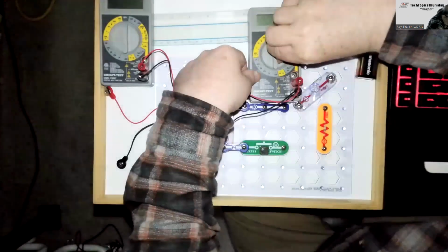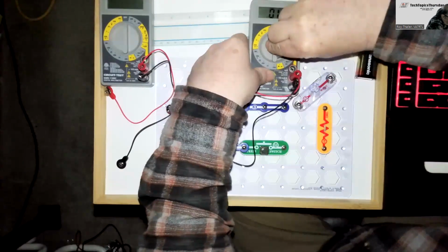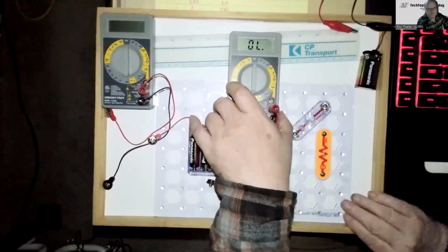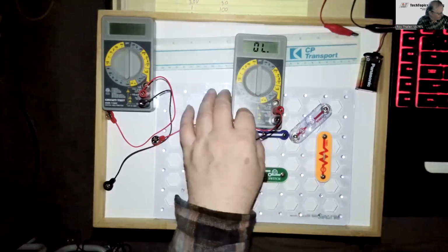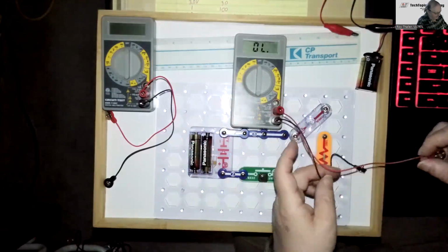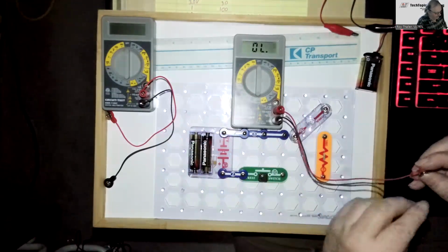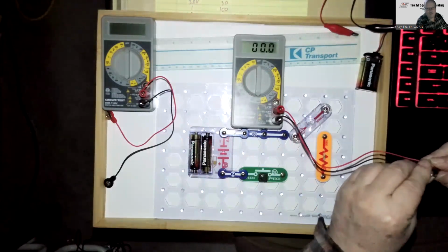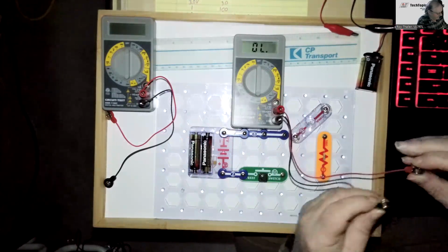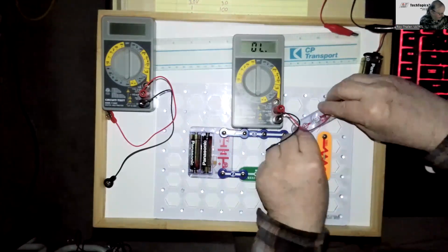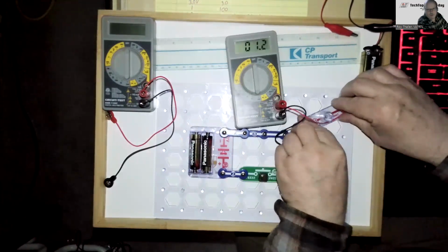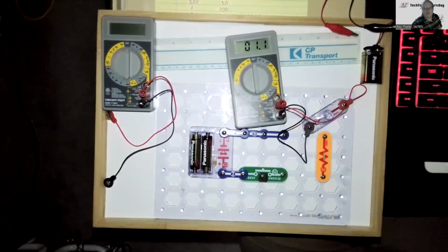And if we turn our multimeter to resistance, we will read low, which means it's open. And then when we short these two things out, it'll tell us how much resistance we have. So it'll tell us 0. So now when I put it across the load here, it's going to also give me a value. So it tells me it's about 1.1 ohm.